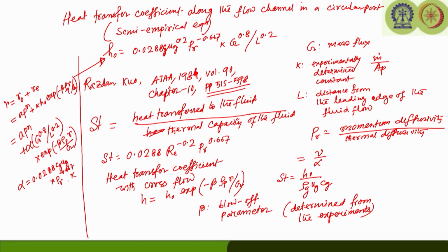So, k is a constant which is dependent on the interaction of the flow parallel to the surface and the blow of gas from the burning surface. What I am saying is, the blow up, you should remember I am talking about this one. The gas is coming out from the propellant. So, this is the burning propellant, this is the propellant surface and the cross flow is coming from here. So, here the cross flow which is UG and this is the blow up.